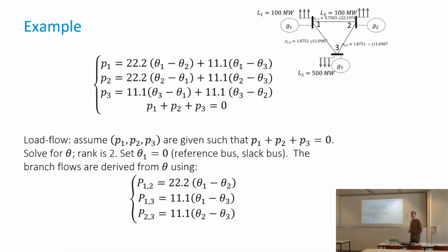Fortunately, because if we reason in terms of load flow, a load flow is considering here, give me the injected powers. For a load flow, I need a slack bus or some kind of swing bus. So here, if I assume node 1 is a slack bus, that means it is the one that does the power balance. Whatever P2 and P3 are, node 1 will balance it. So node 1 will do P1 that is equal to minus P2 minus P3.